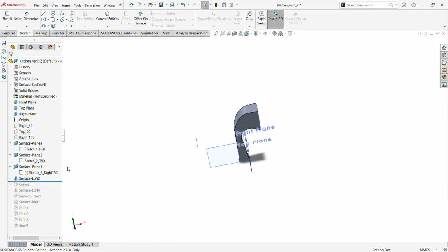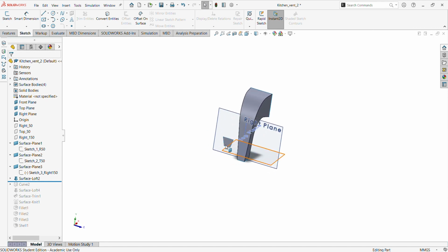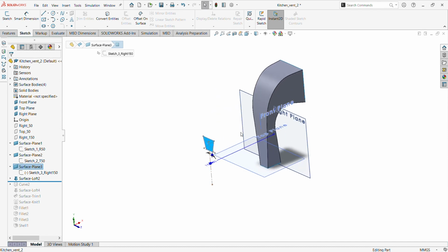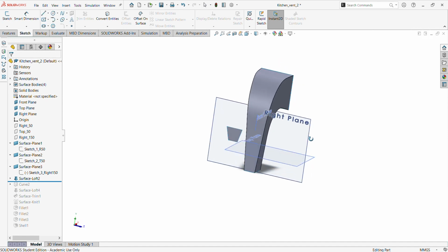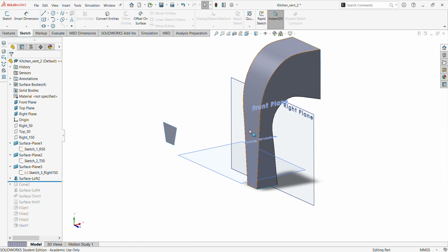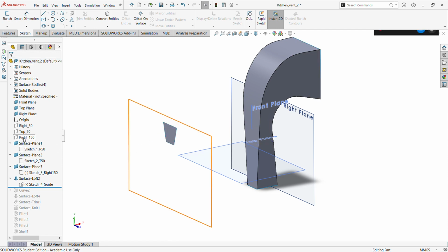Okay, now the second challenge will be getting this surface to build a loft with this surface, because lofts also work with the principle that the faces, the sketches or the surfaces must be well defined, but this surface is a continuous surface, so we had to do a bit of construction. By going back to this sketch, I can take that so you understand what I did. So we'll go back to the plane that was used to do this sketch, because we are going to flow our loft to the other surface from here.